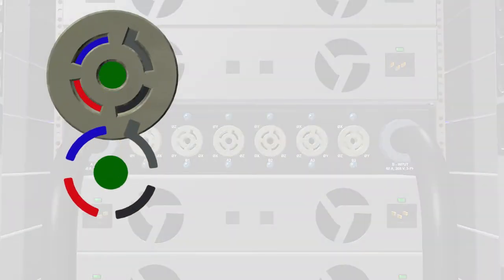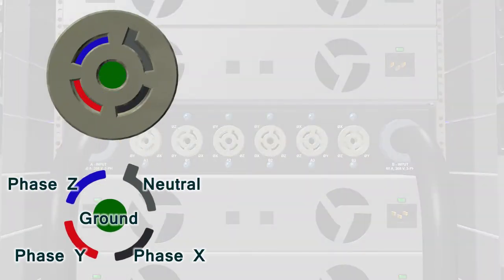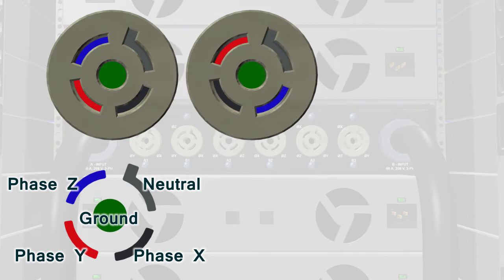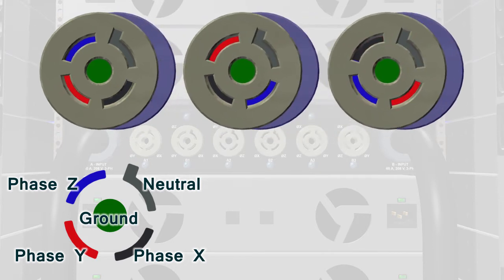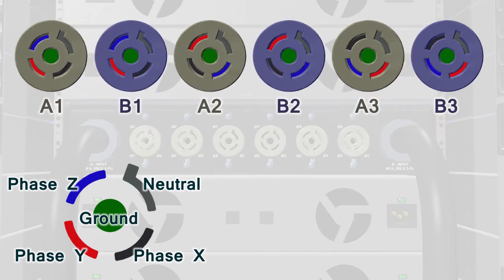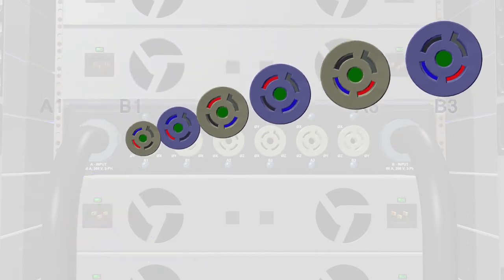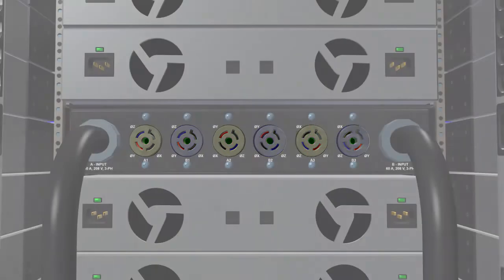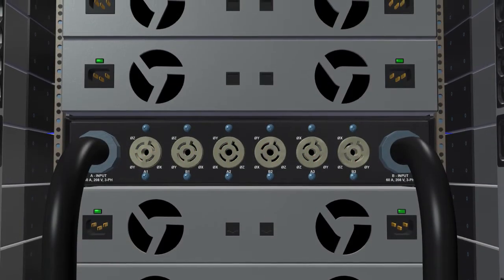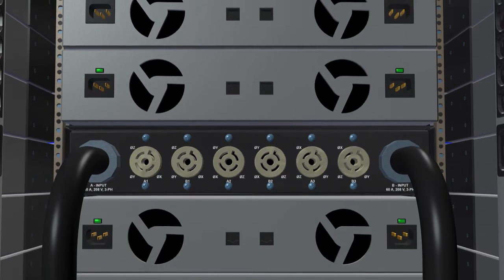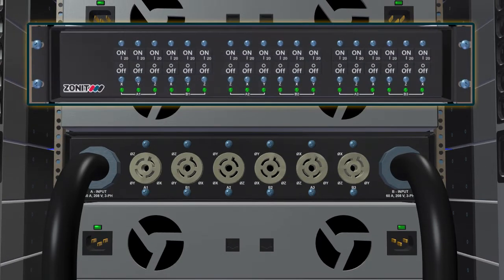Fourth, the patented phase balancing features of the Z-PDS system will automatically, statistically balance the loads on each of the 3 input phases from the AB power sources, so it does not have to be done manually. Fifth, the 3-phase output receptacles of the Z-PDS units have each individual hot lead protected by a separate circuit breaker.